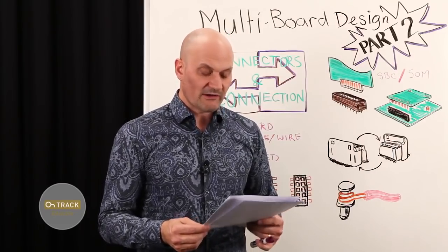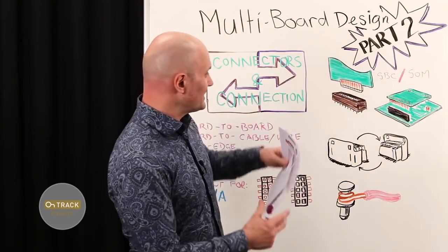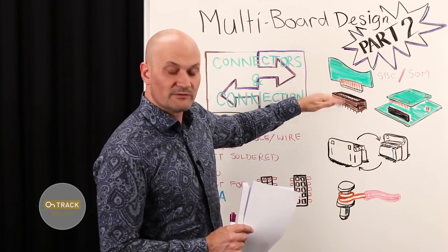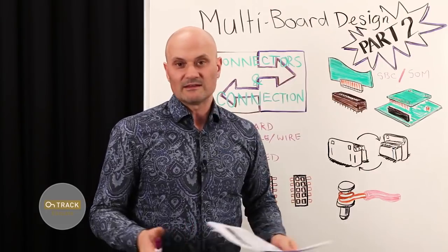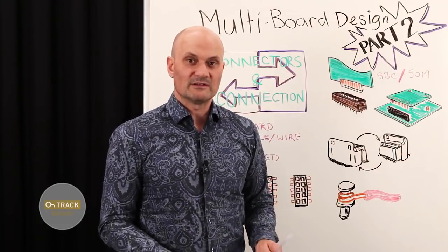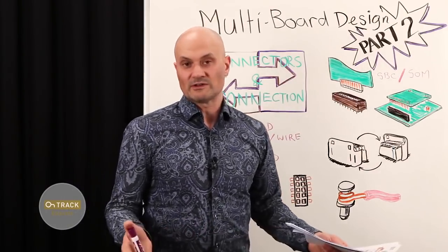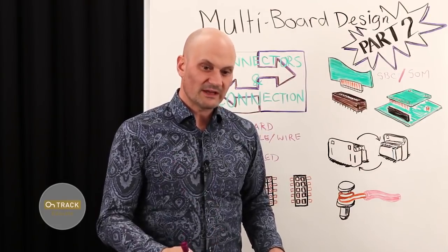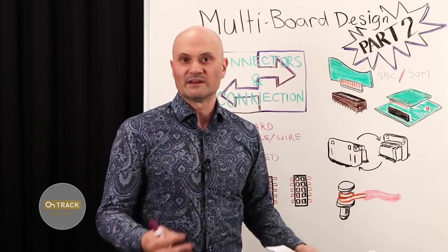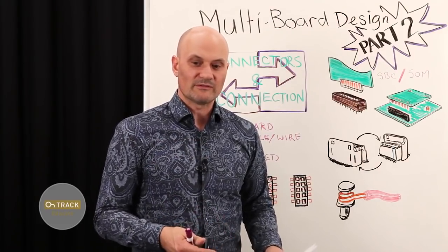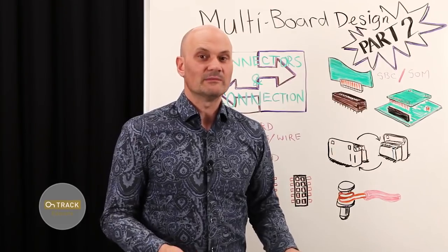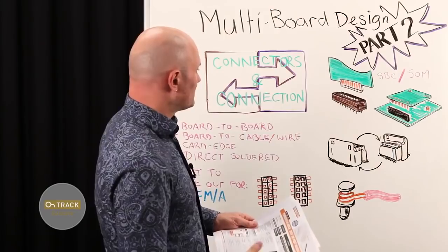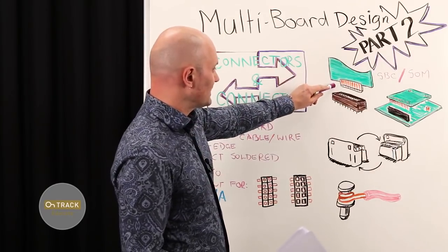So if you're going to produce something more like a card edge connector based peripheral that's going to be inserted and removed several times, then that might be more of a consideration as to duty cycle. So by duty cycle, I mean how many times can you insert and de-insert the assembly before the contacts wear out and become unreliable. I mentioned that's probably even more of a concern for a card edge connector.